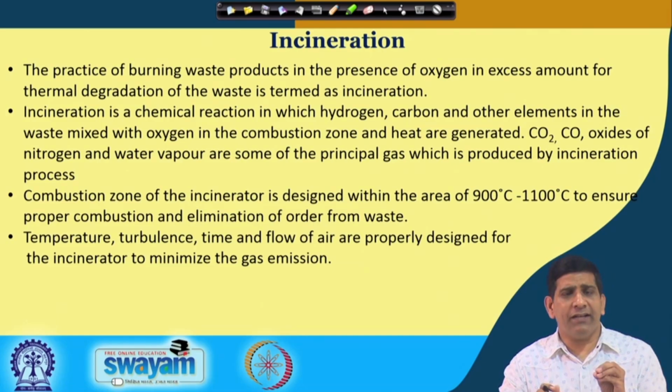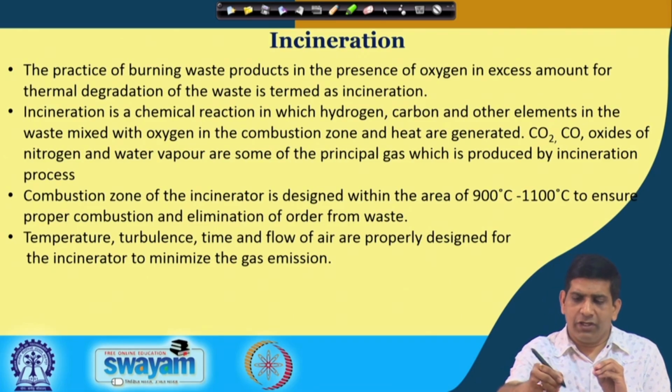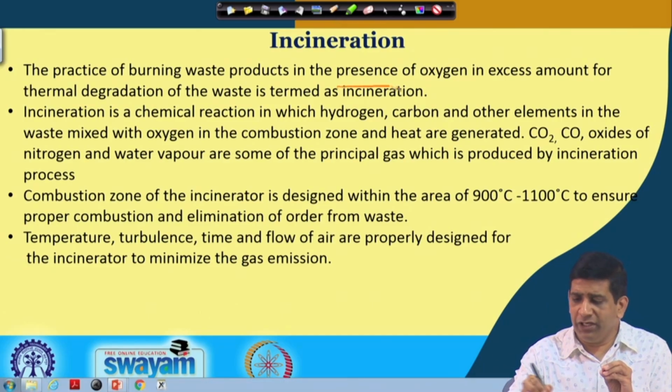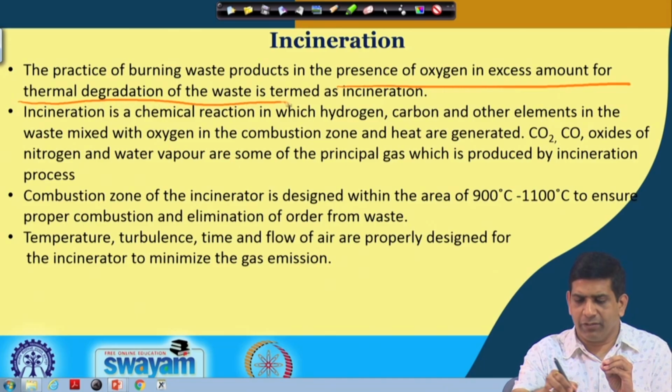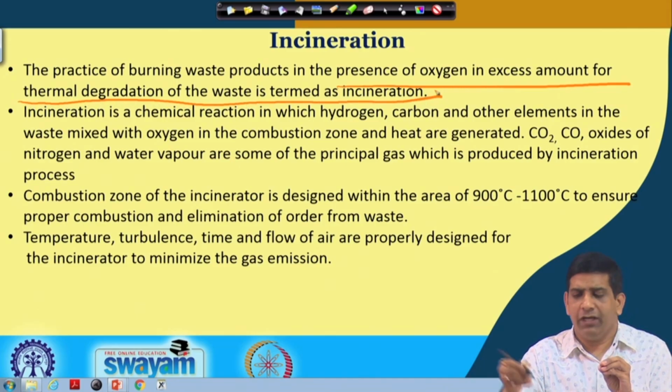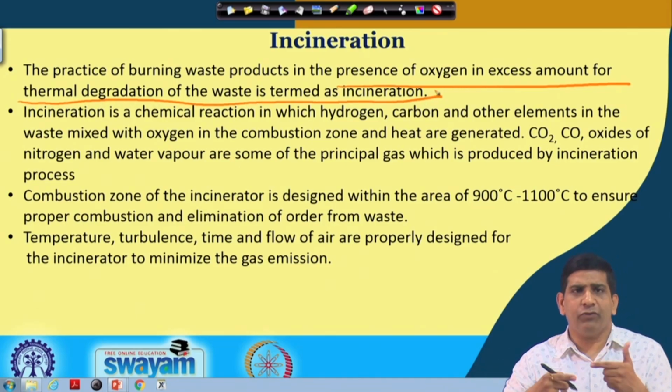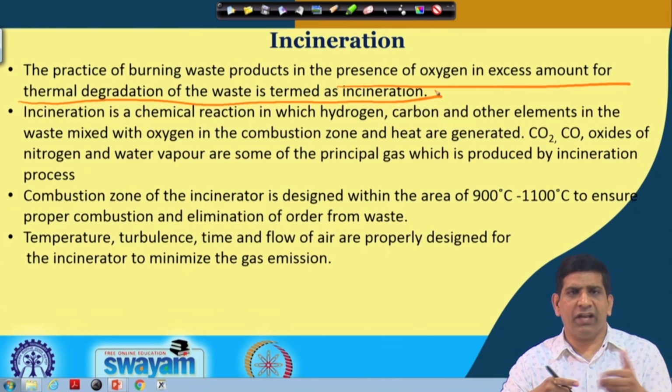So incineration plants, waste to energy plants: pyrolysis was in absence of oxygen, while waste to energy incineration is actually in presence of oxygen. Here you are doing the thermal treatment, the thermal degradation of the waste, in excess oxygen. So you are adding air, we have to supply air, and it's essentially a combustion process. As you know, combustion is an oxidation process, so air is required, oxygen is required.